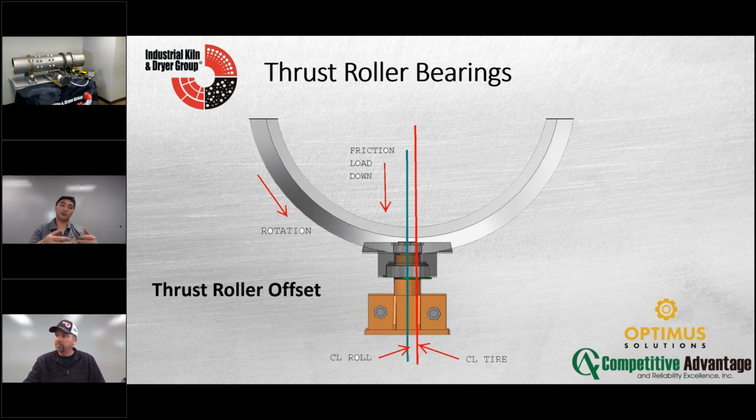So you can destroy the thrust roller if it is not on the right offset, so just don't do that. It's practice to keep it over on the down turning side. We have had a group where that happened, and the unit was two or three stories up, and it lifted up, and a big old bang happened.